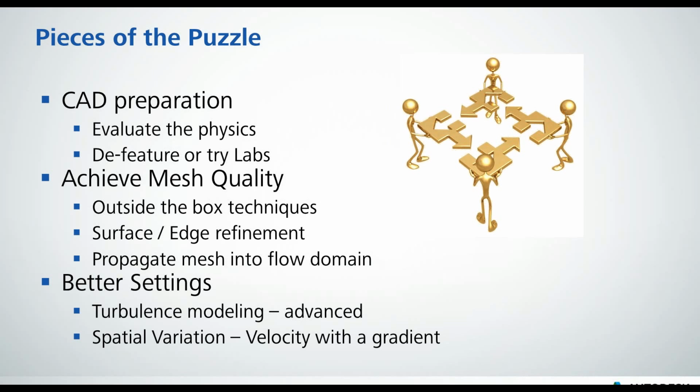I'm going to review our surface autosizing and edge refinement techniques. These are some techniques that you can leverage to achieve some really nice meshes. And one thing that's a little bit particular to external flow, but internal flow with large cavities has the same problem: how do you propagate the mesh into the flow domain? So we'll cover that when we go over the mesh quality.